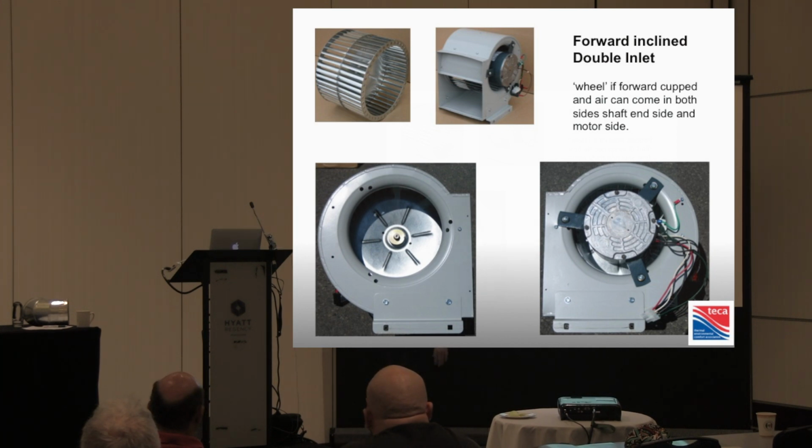And the other good thing about it is when you stick the motor right in the inlet, it has a huge degree of cooling, because the only thing that limits blower life today, short of stupidity, is overheated bearings. And overheated bearings are when your motor overheats, and overheating can be avoided to a large degree by the packaging configuration right now, which is thermally superb.